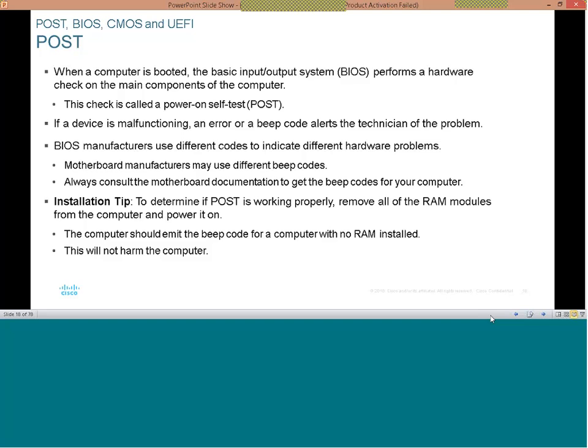What we're saying here is that once there's a break in the bridge of communication from either the RAM or the CPU, you always get this beep code alert, telling you that something is wrong. And once you troubleshoot, you're able to resolve the problem by either replacing the device or clearing up the dust from it.